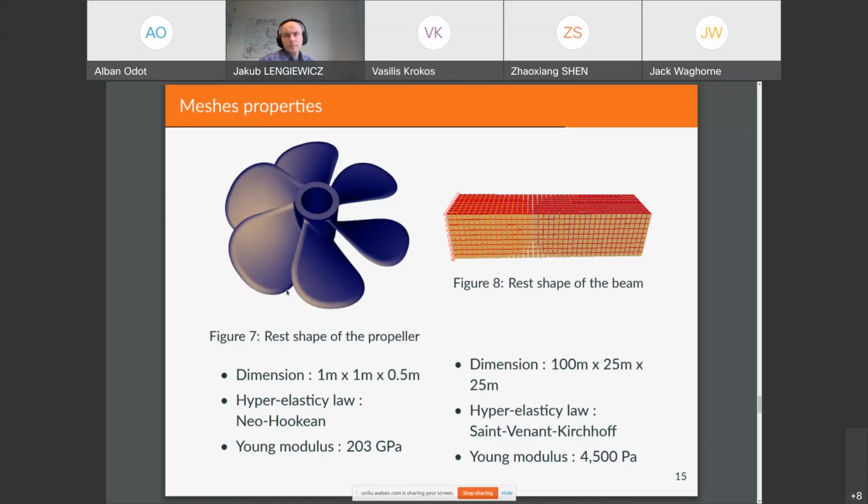But I tried multiple hyperelasticity laws that were publicly available in SOFA and achieved similar results, even though it converged faster with the Saint Venant-Kirchhoff than the Neo-Hookean, due to the simulation behaving a bit better with Saint Venant-Kirchhoff, because Neo-Hookean is very sensitive to element inversion and compression, for example.